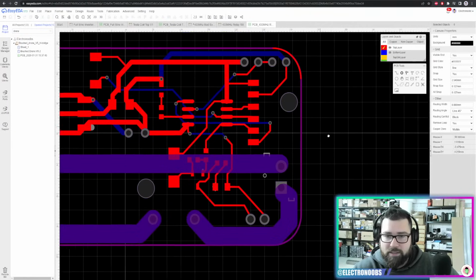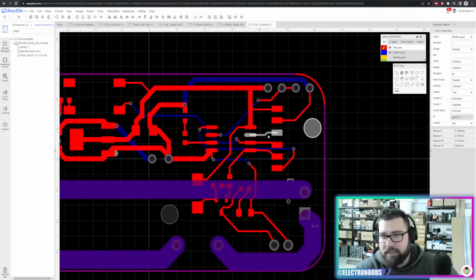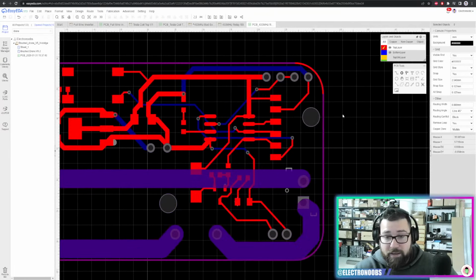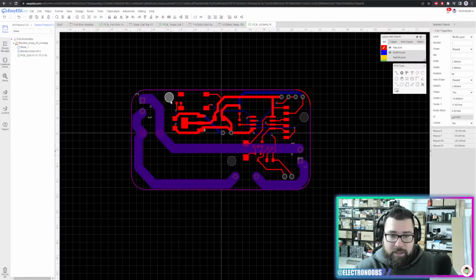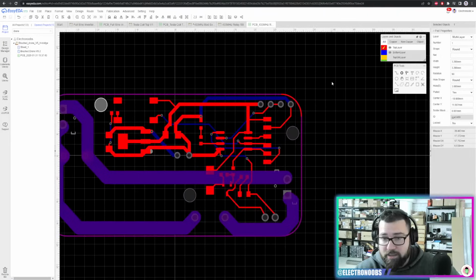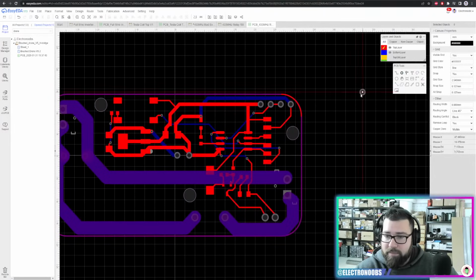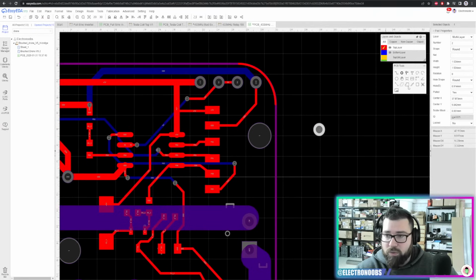How to add external pads. For example, this pad here is connected to nothing, and this doesn't appear on the schematic. But these are just some holes of 3 millimeters, in case you want to screw this onto some sort of case. So all you have to do is click the pad button and place it here. But as you can see, it will give it a name, it will give it a number, and the name usually is ground, but in this case it's nothing.